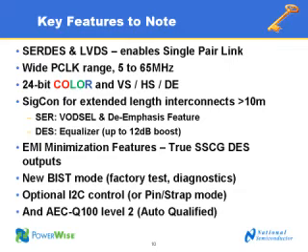Can you tell us a little bit more about what you mean by true SSCG DES outputs? Sure. So the spread spectrum clock, and we'll have another slide that describes that a bit more later, is slightly moving the clock at the output to reduce the spectrum of noise. And in addition to just moving the clock, the data, so remember we have 24 bits of parallel data, is also moving with the clock. So what that does is it reduces any noise that occurs at a given frequency, spreads it over a broader spectrum, and reduces the EMI at that interface.